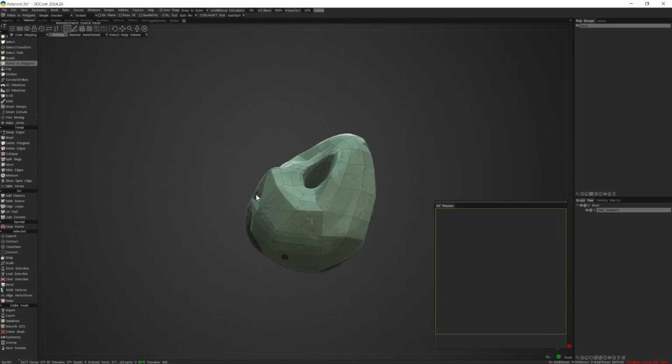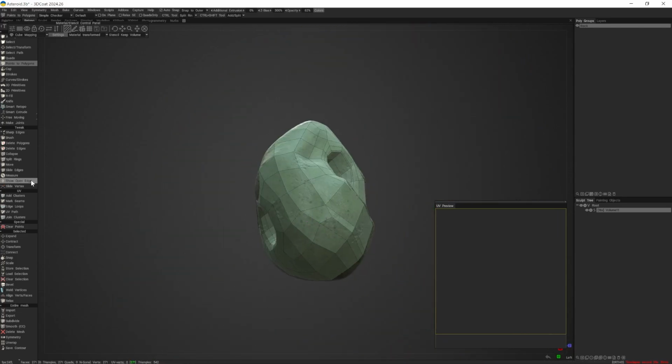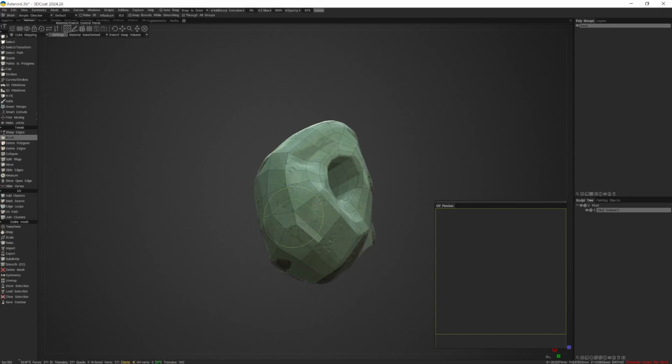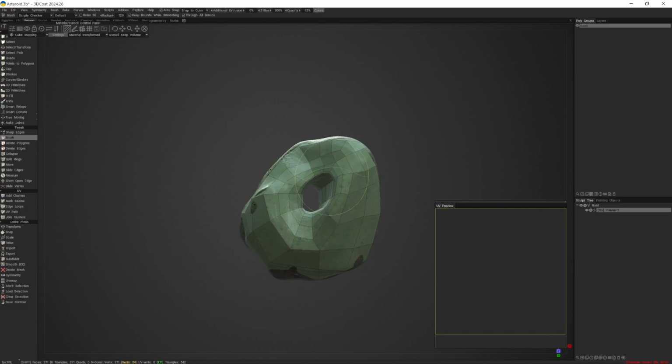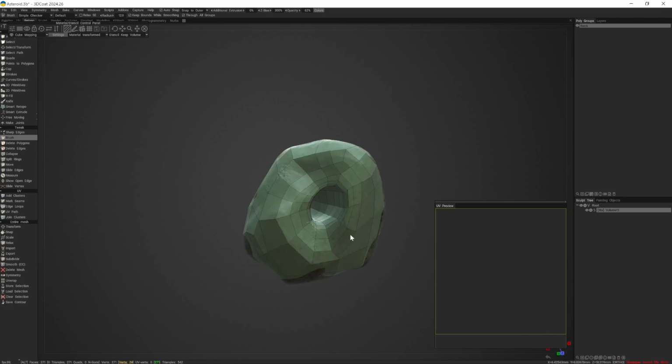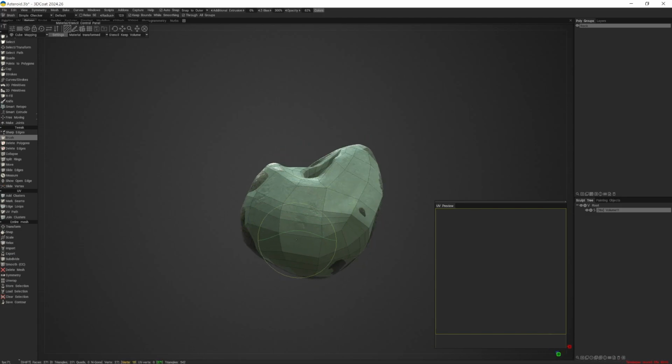All right, cool. So now that we have this, we can go through and I can use a smooth tool or a brush tool. With this, I can shift geometry around if I left click. If I hold down Shift, I can just smooth out the geo. I can smooth out that retopo mesh and it slides across the underlying sculpt. So that's kind of nice.